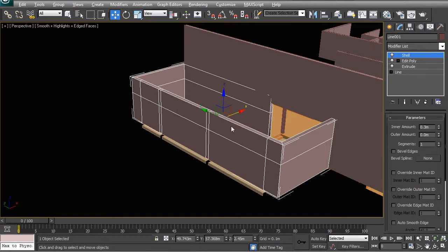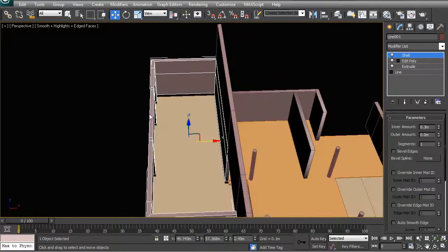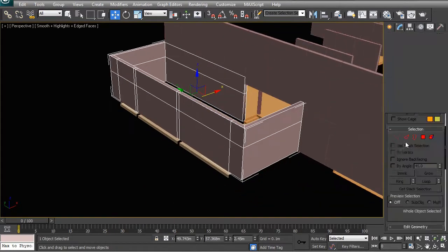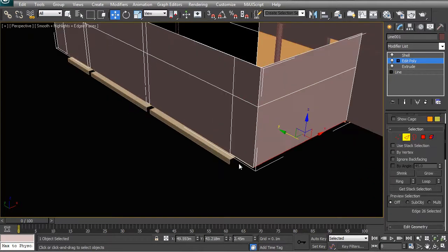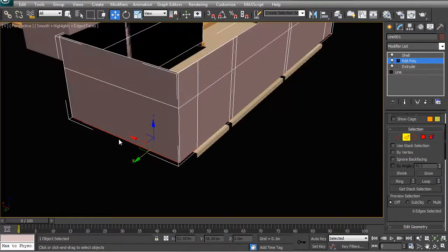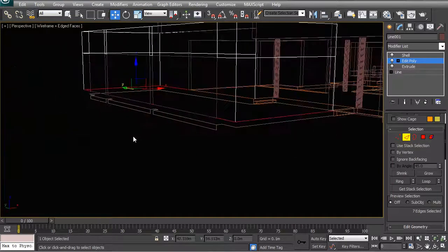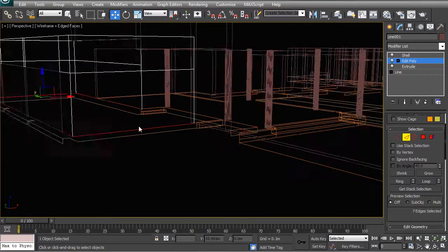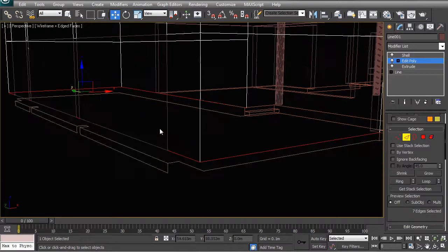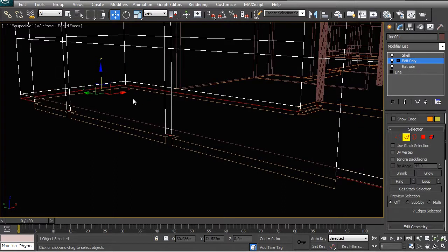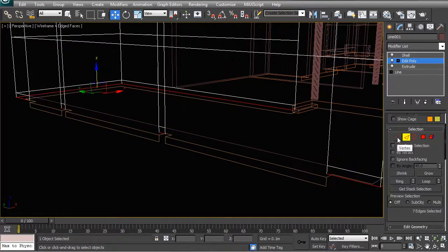I also want to let you know that once you have floor slabs in place and you can see that the walls need to be edited, it's a good time to make those edits. Instead of just pulling down these edges, a little tip is to try to keep an edge in place wherever you have your floor slab. For example, if the upper level has a floor slab at this height, which happens to be 2.45 meters, try to keep that line in there so that you can snap onto it and start to read your height differences.